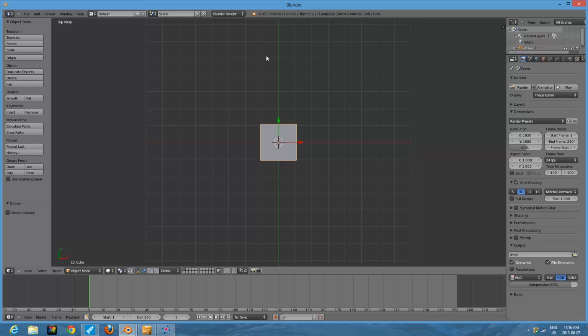Okay, so I know in the video it's hard to see the grid. If you see this grid that's around it, there are 2 view modes. There's perspective mode, which I'm in right now, the 3D viewing mode. If you hit 5 on your numpad, it turns into orthographic mode, which is looking at everything in a 2-dimensional image. I find orthographic mode easier to work in, but I know on the video you can't see the grid. Right now I'm looking at a bunch of little squares as a grid, and you should see it too if you actually go into Blender, but the video doesn't pick that up. So sometimes I'll be talking about squares or grids, and if you can't see it on my video, when you're in Blender you'll see what I'm talking about. Okay, so I would hit 5 to get into orthographic mode.